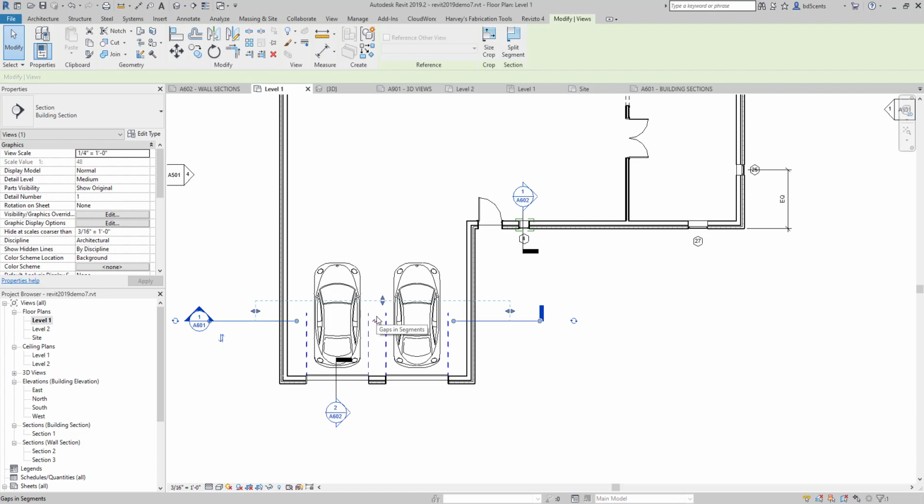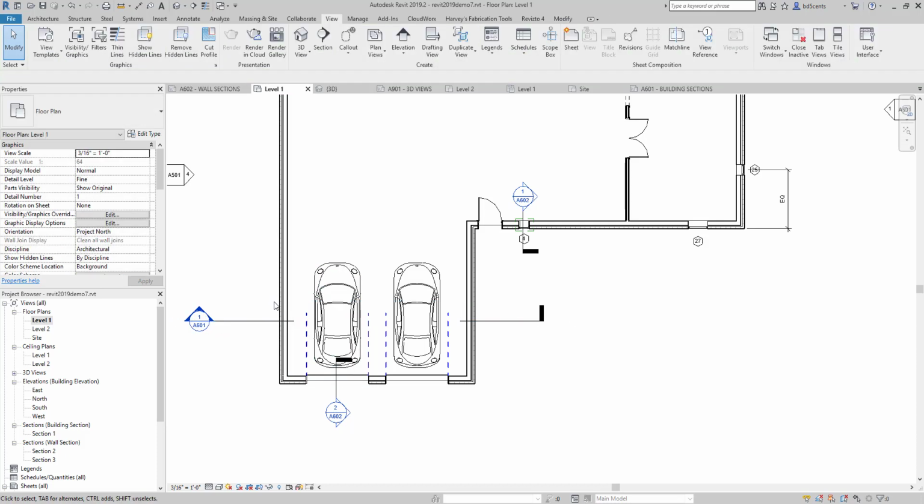We want to left click on the Z so that they break the sections into two parts, and you can drag the blue dots, just like we did, and grips to show the part of the section line you want. Want to join the section line into it again? You can select the line again and highlight that button and they join again. Note, you can only go as far as the crop region boundary or green lines on the split section. So you can only drag these as far. Actually, you can go further. I just recommend keeping them within the wall so that it's very clear.